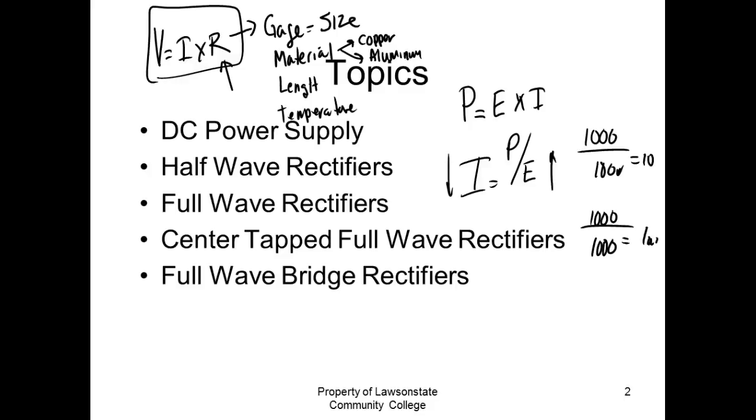So what we'll do is we'll step it up for what? Transmission. And then the closer we get to us, we start stepping it down until we get it to our house. And we have two voltages available in our house. We call them 240 and 120. We run our high wattage loads on 240, and we hide those plugs, or we direct wire them, right, because it's very dangerous. And then all our plugs are what we call 120, because it's safer. Y'all understand that?